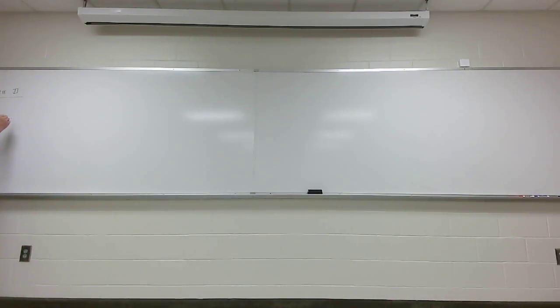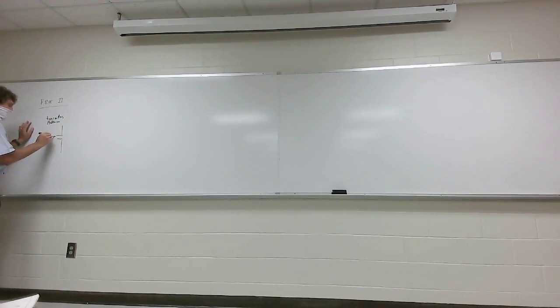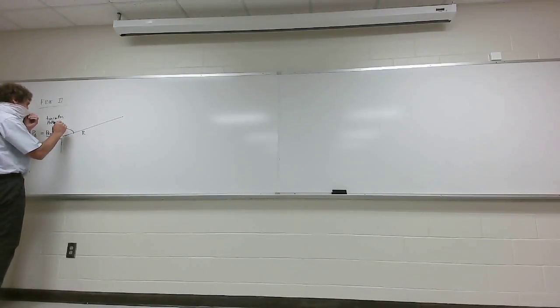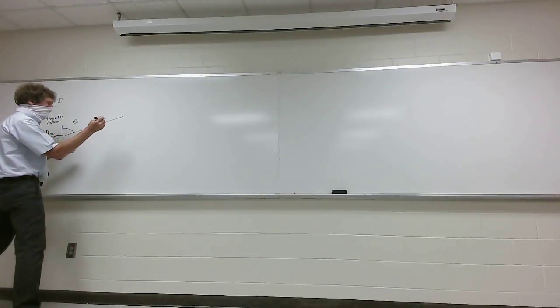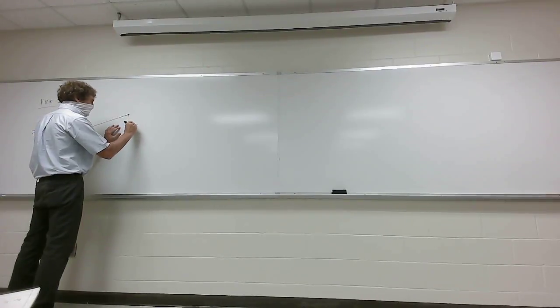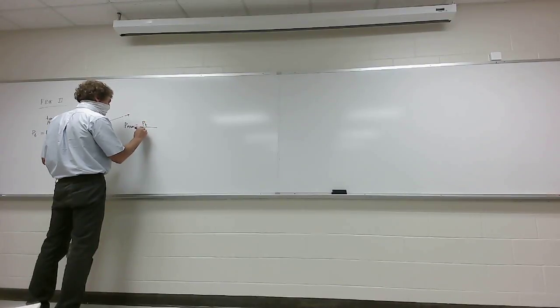So when we had an antenna, this is the transmitting antenna, and you could assume it transmits some P radiated. Sometimes it'll be P transmitted in Dr. Wentworth's book. It's the total amount of power transmitted. If you're out a distance R away at some angle theta, then the actual power density here is equal to simply P transmitted or P radiated over 4 pi R squared.